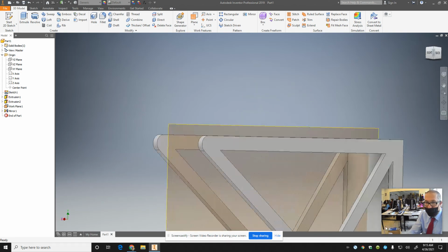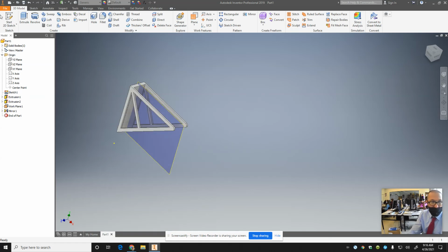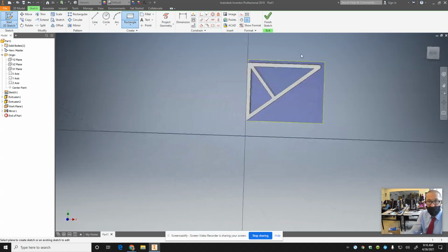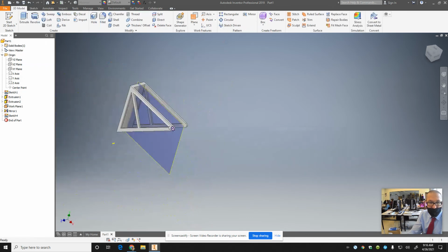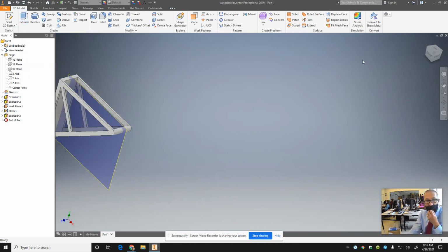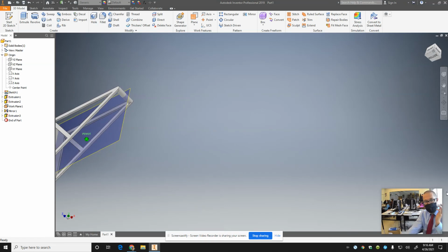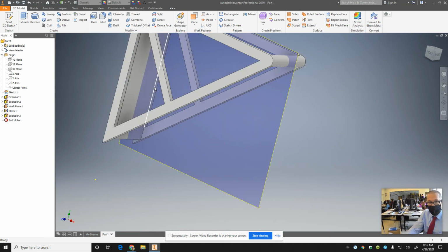Now, you really want to get your plan put across, and then I'm going to go in and add the pegs, right? I'll start a sketch here. I'm going to project some geometry here, that arc. I'll draw a circle there. Finish sketch. Then I'm going to extrude across. Extrude. Direction. I got to make it solid. I'm going to go to next, and it'll connect up to that other side. Alright. So that's how I connect across. I draw on one side and send it through. And you start going from there.